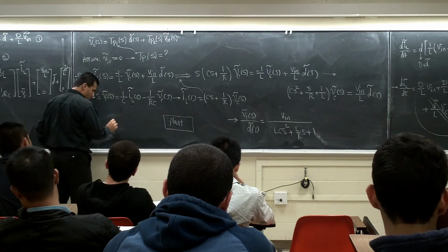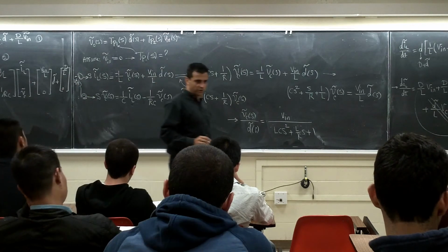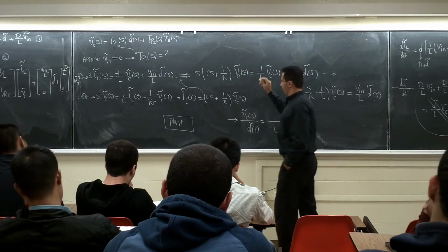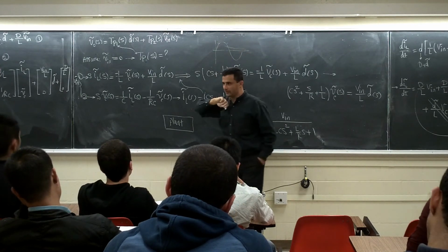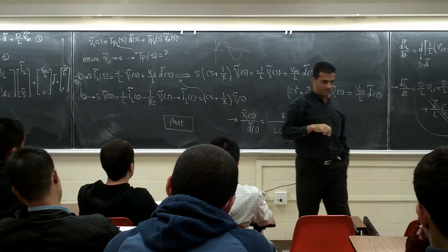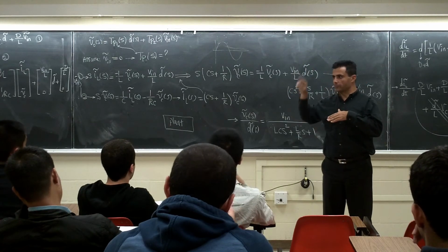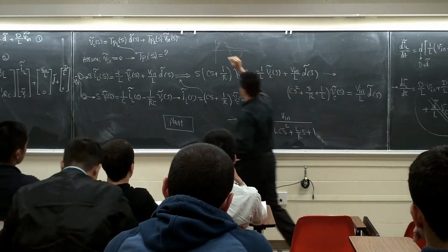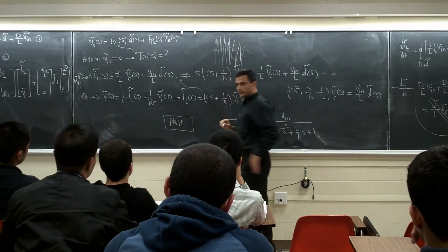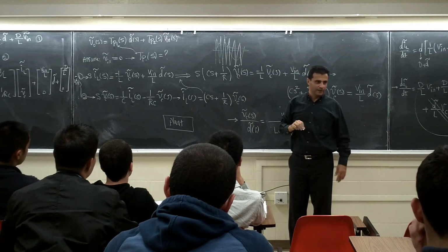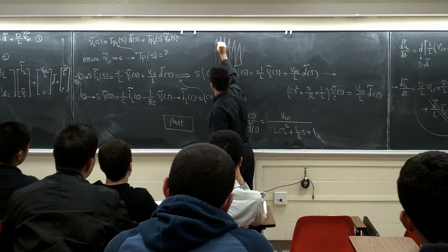Like the inverter project you are working on, you calculate your MA, right? MA is going to be something like this. What do you do with this MA? You cross this one with a triangular waveform, and what is the output of this one? You get something like this. You get a pulse here, right?